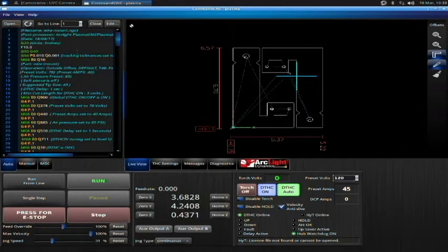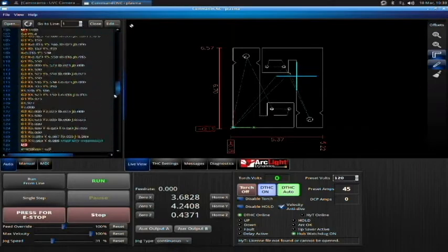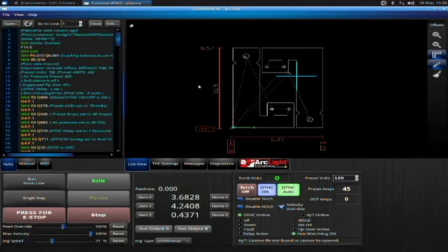Okay, so this here is your G code. Okay, this X here represents the current position of your Z-axis. Now this is currently off the machine. It's saying it's on the machine home. Okay. Now we'll have to zero this out again to set the part home.